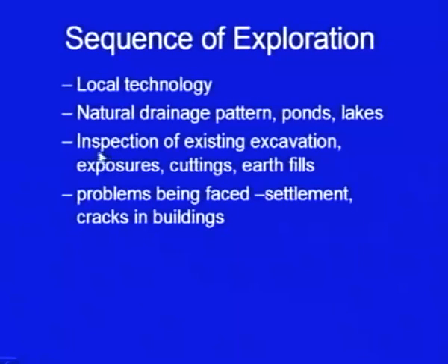Then also inspect the existing excavation, try to find out if some exposures are available, some cuttings are available, some earth fields are available. Then you can see those sections and you can have the idea about the subsoil strata. And also you look at the buildings, if there are cracks in the buildings because of some foundation problems, if there are excessive settlements, they also speak of some problems. So, they also speak about the subsoil strata. All these things you should get when you visit the site. So, visiting the site helps us in a big way, you get lot of information from that.